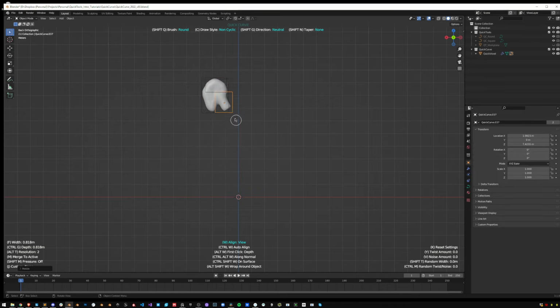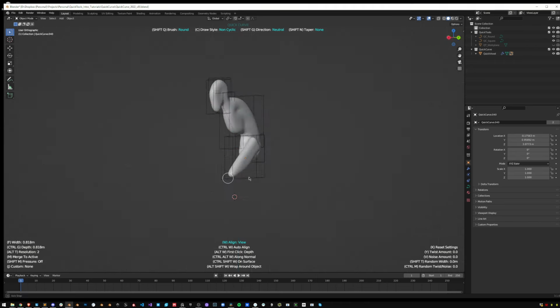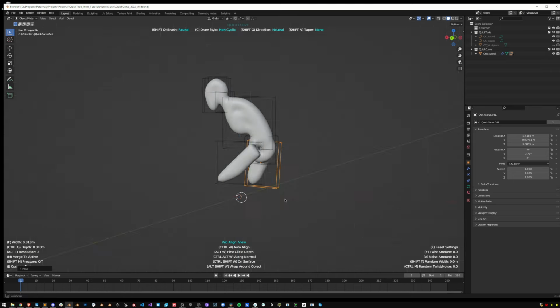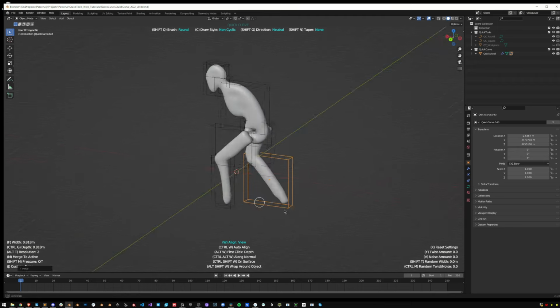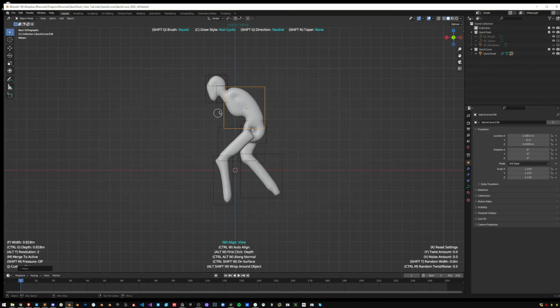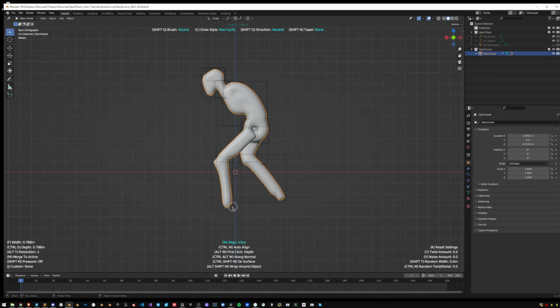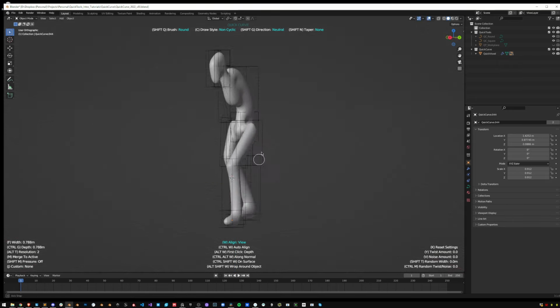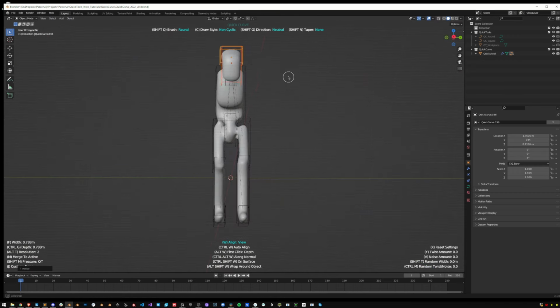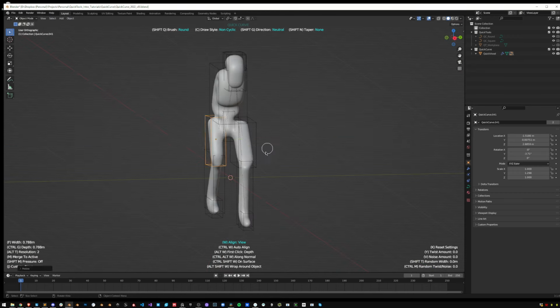So here I'm showing one of the new features, which is Voxel Modeling. So you can go into the Control D menu, and there's a little voxel resolution setting and a smooth setting. If you turn that up, basically every curve that you draw will be remeshed and smoothed, depending on if the settings are active. And the nice thing about that is that it's all kind of live. So you can move the curves after the fact. You'll see it's all remeshing kind of at once.